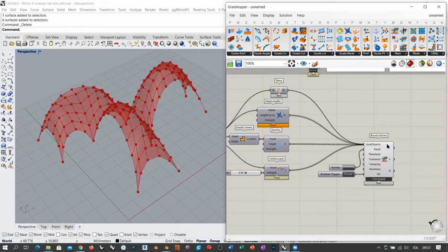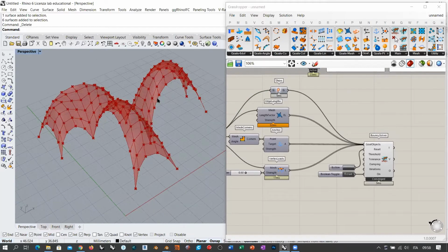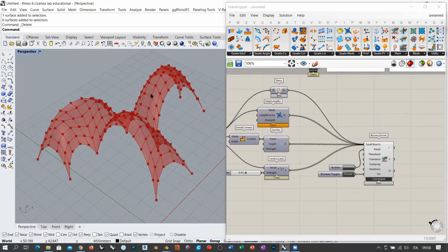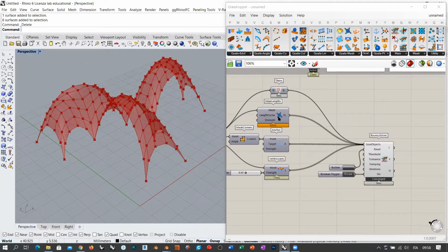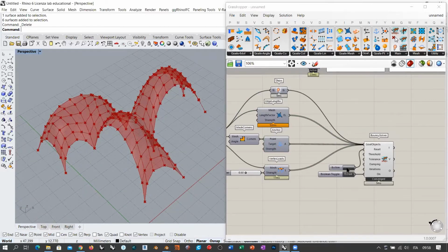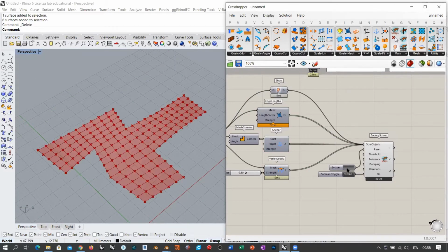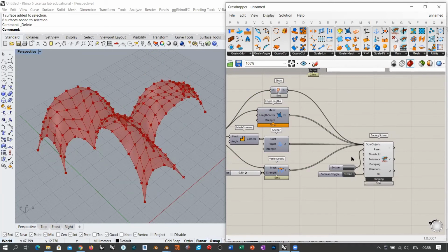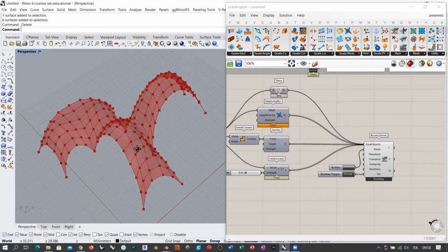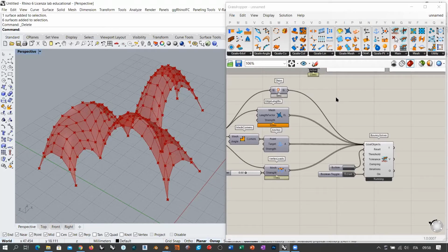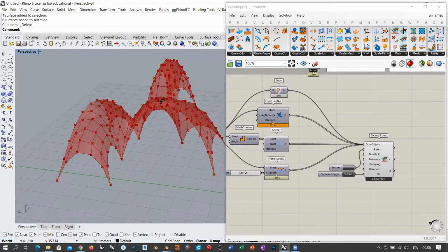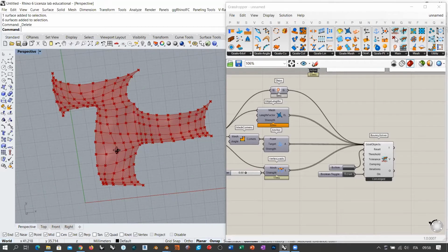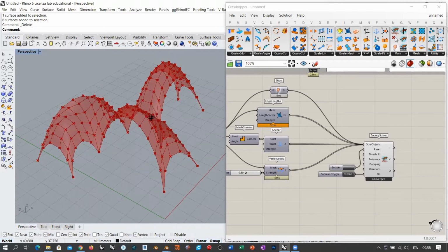So now you see that the deformed mesh is displayed. It is just the consequence of the deformation that we get for springs due to anchor points and loads. So it's just visualization. But now, if you run the simulation, you will also see the mesh deforming accordingly. But remember that the mesh doesn't interfere in the simulation. It's not necessary for the simulation. So now we have this object here, and let's see what we can do with this one.